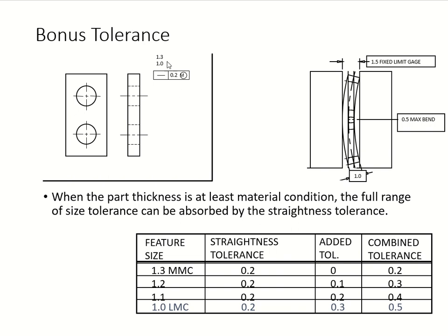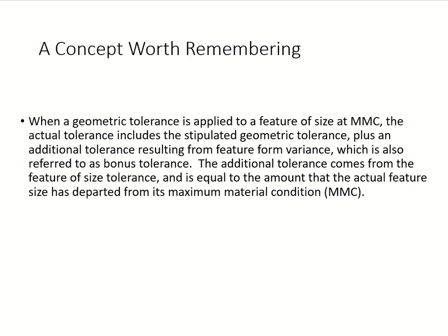And you will be adding away from this, going down each unit, because our tolerance is in 1 decimal, so 0.1. So you're going to go in increments of a decimal, keep going all the way until you get to your LMC right there. So you know that the added tolerance goes 1 time, 2 times, 3 times from your MMC. And this is what we call moving away from its maximum material condition towards least material condition. Be careful with that.